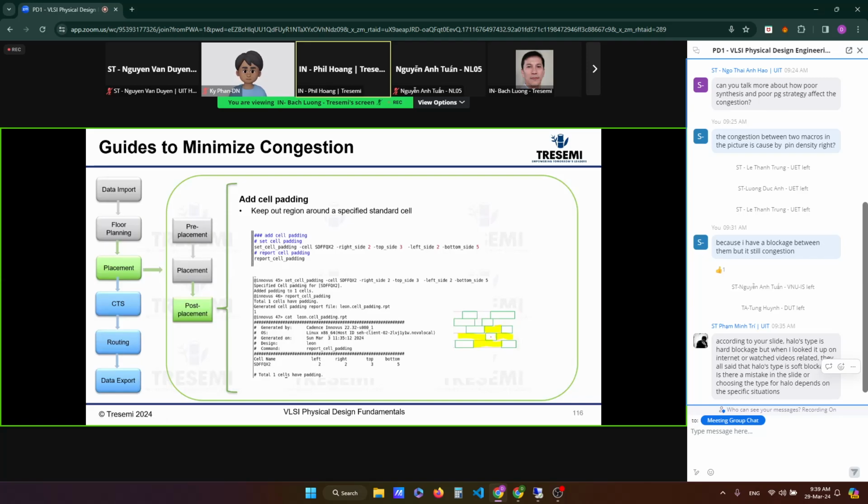They are congestion aware, but timing driven is very high in priority. So if we don't give the placer some help like this, it will bunch things together based on the speed requirements.